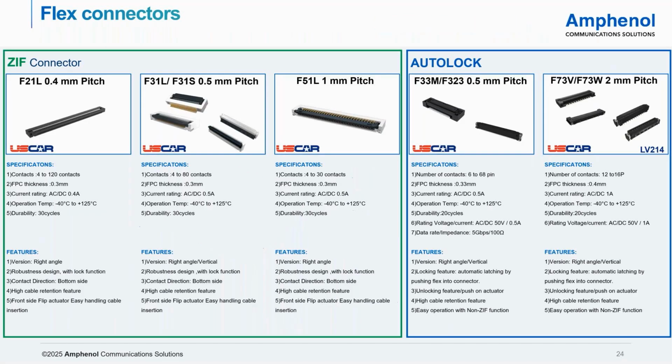We have looked now at the newer flex connectors, but we also have legacy flex connectors called ZIF and Autolock. ZIF stands for zero insertion force, and Autolock stands for you push in the flex and it locks automatically. Zero insertion force means, as you can see in the middle picture on the top, that black part is an actuator. The black part will be vertical. We will place the flex inside